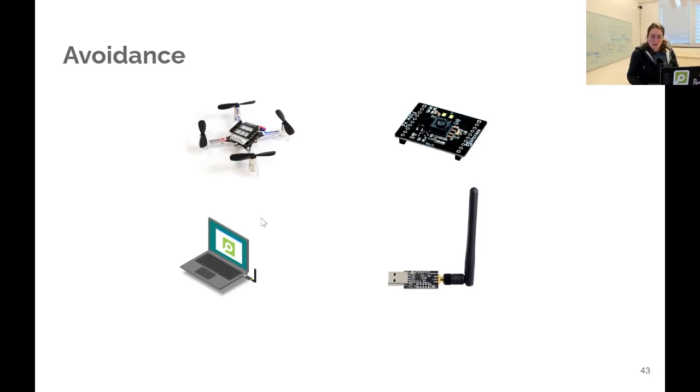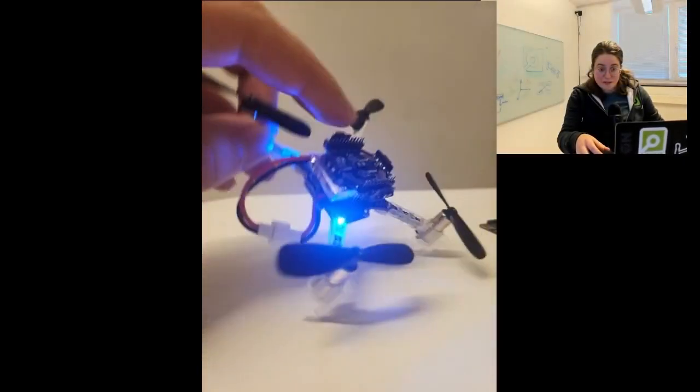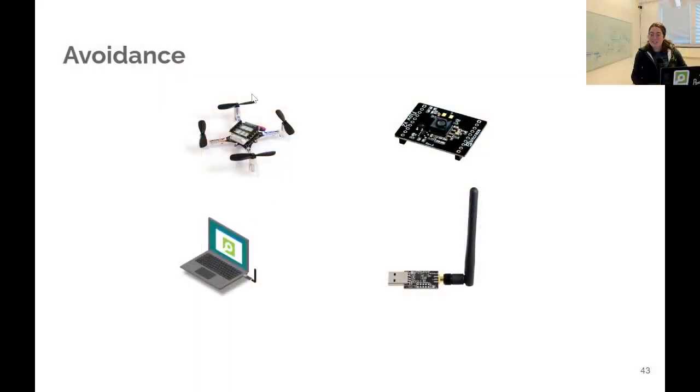Well, of course, as you can see, I've already spoiled the surprise a little bit, because I already added a multiranger to the Crazyflie. So that already spoils the next part. You need a multiranger or a camera or something that's able to observe the environment, not just looking downwards. Because if you have the flow deck, you cannot really do that much avoidance, because it's only looking downwards to determine its own velocity. So it's pretty blind.